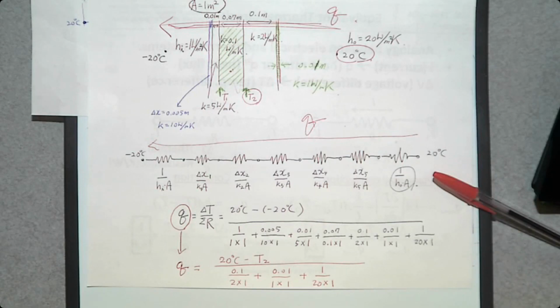That's the temperature only at the interface between insulation and the wall, because insulation has many temperatures in the direction of heat transfer. There's not just one single temperature. If there's only one single temperature, that means there's no heat transfer through that insulation.